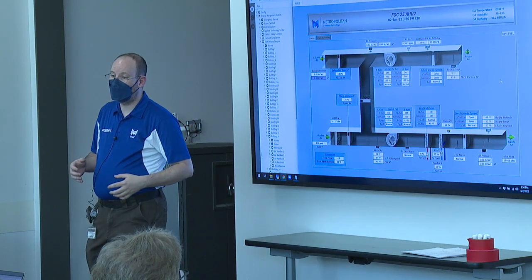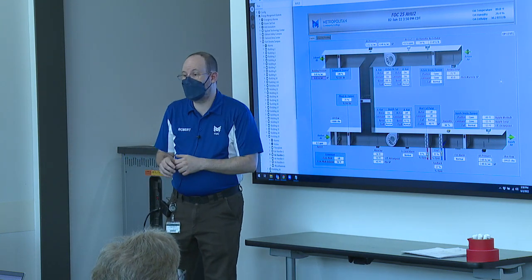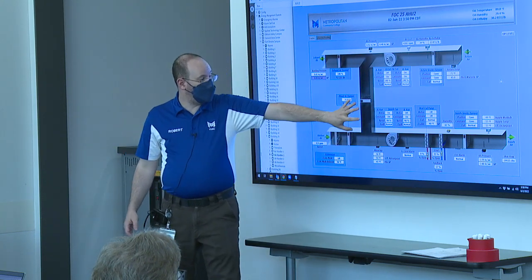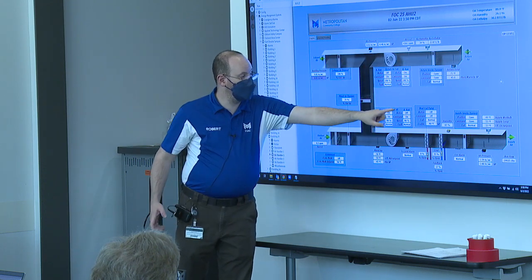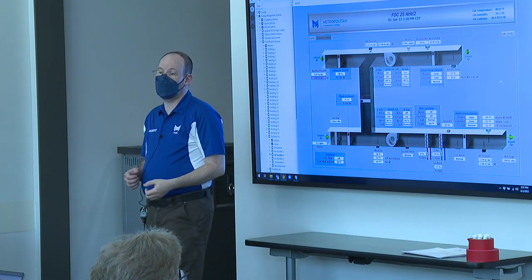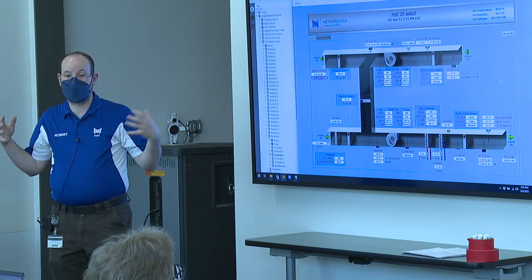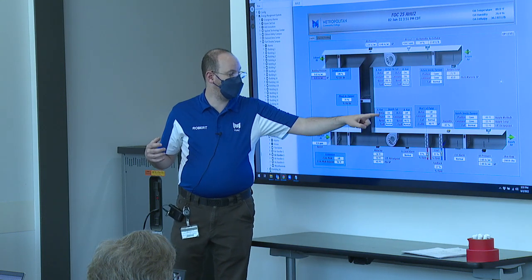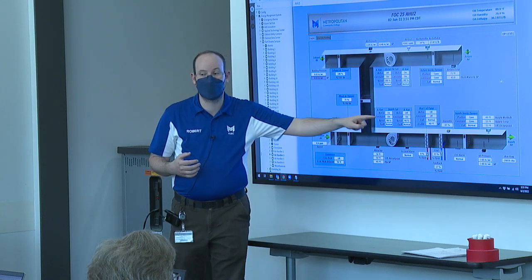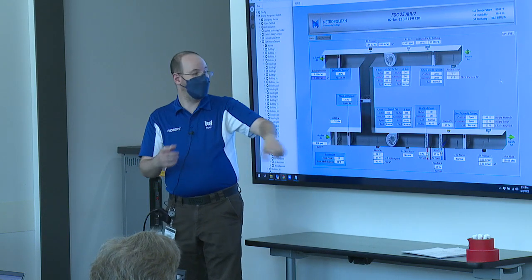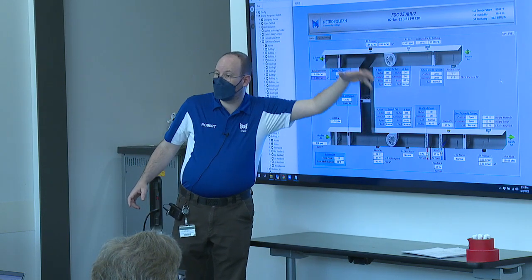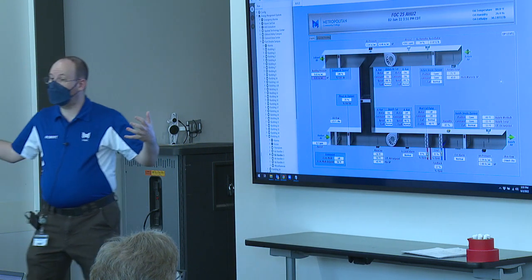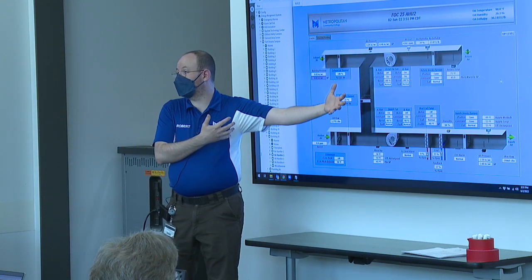Okay? You have to think about how you're going to organize the data. You notice here we've got some discrete boxes showing up. So all of our supply fan data is grouped together in this box so we know it's all associated. Okay? That does a couple of things for us. It saves us label room. Instead of having to say supply fan status, supply fan command, supply fan speed, we grouped it all together, put the supply fan at the top, and assume we're going to know that it's supply fan. Right? Looking at the graphic, it's pretty logical to see.